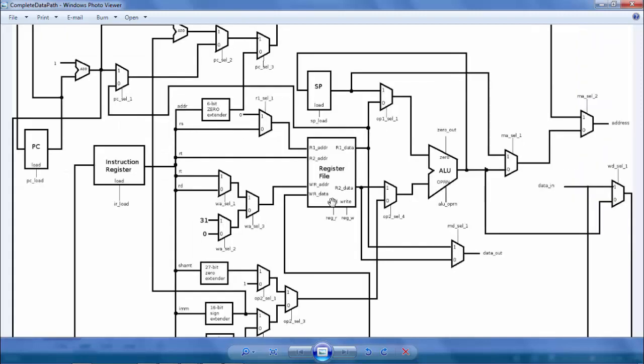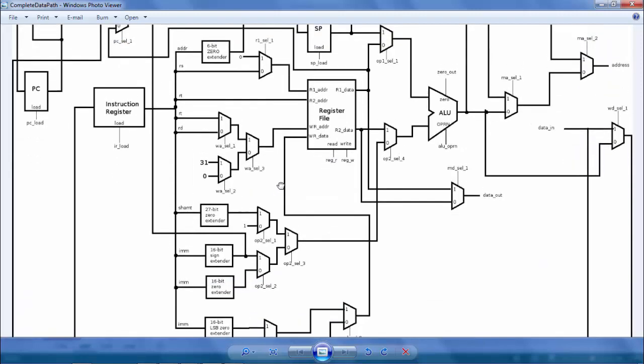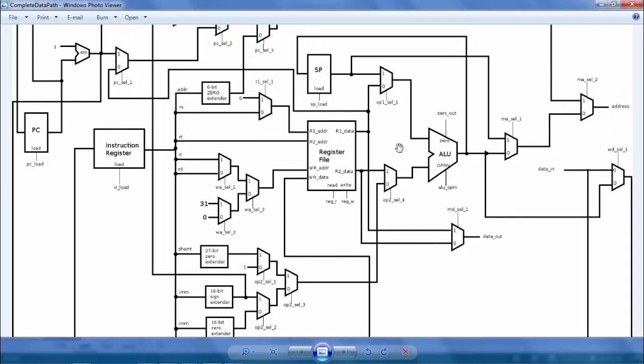Then we can group the others as operand selects. It is all related to the ALU operation, and if you trace back the two inputs, it is like OP1 select 1, and then it's pretty much there. We don't have anything like OP1 selection 2, because we just need to distinguish the operand 1 of the ALU between two different data sources.